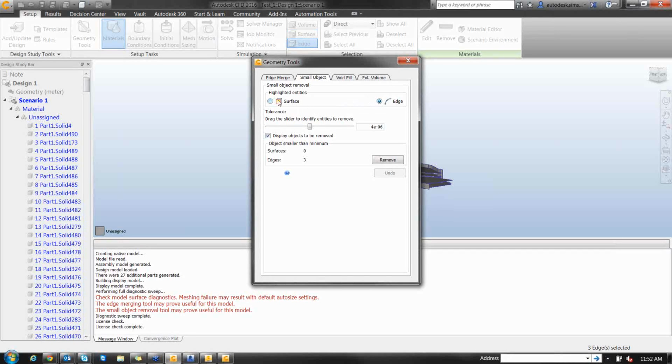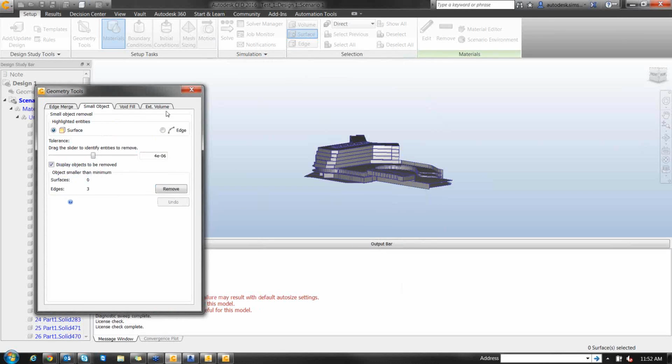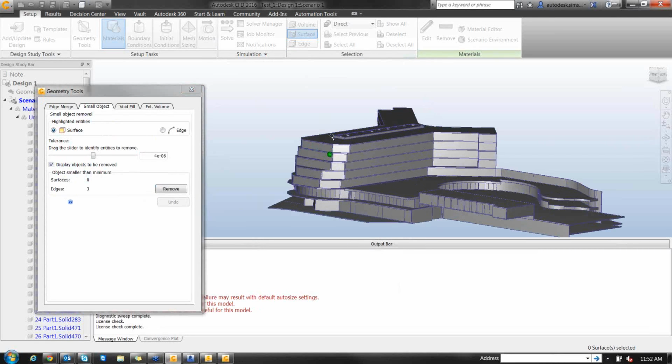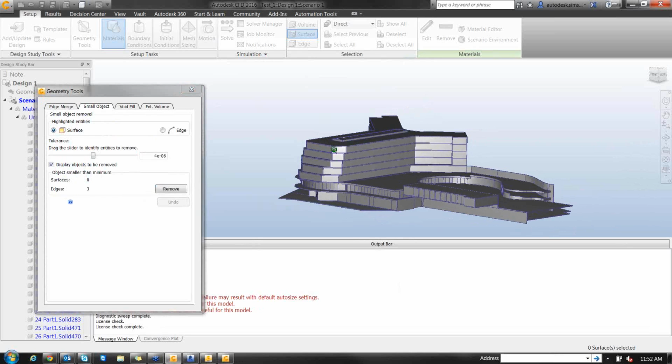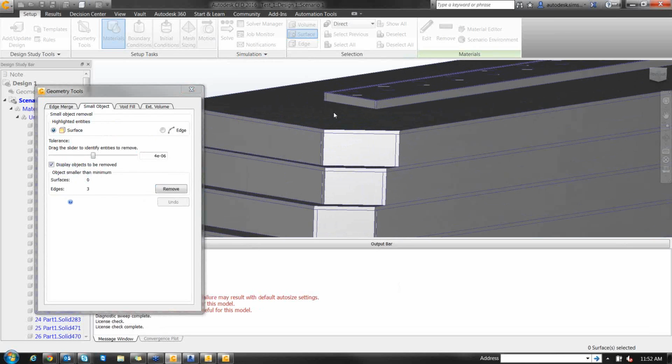And I have seen some people try to do that with the interferences, remove all the bodies of that, and more often than not, that creates more issues. Because what's going on here when you remove, for instance, a surface, it visually creates a hole in that model, and that hole needs to be smaller than the neighboring mesh that it eventually has. And if it's not, it basically becomes like a drain. As the mesher tries to smear over that hole, the elements are now so small that it actually feeds into that hole.